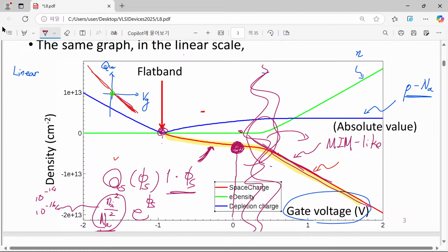So an extremely small number. However, when we have high surface potential, meaning a large bending of our energy band diagram inside the semiconductor, then this exponential factor can overcome this small leading coefficient, and eventually this term will overcome the slowly varying linear term.